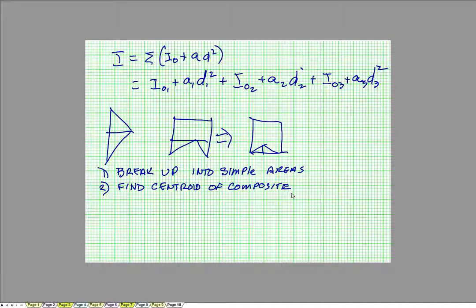And remember, finding the centroid was a bunch of steps in itself, right? Find the individuals, and then transfer them and do some calculation to determine what they are. Once you find the centroid, you need to calculate the distance for each shape to the centroid.